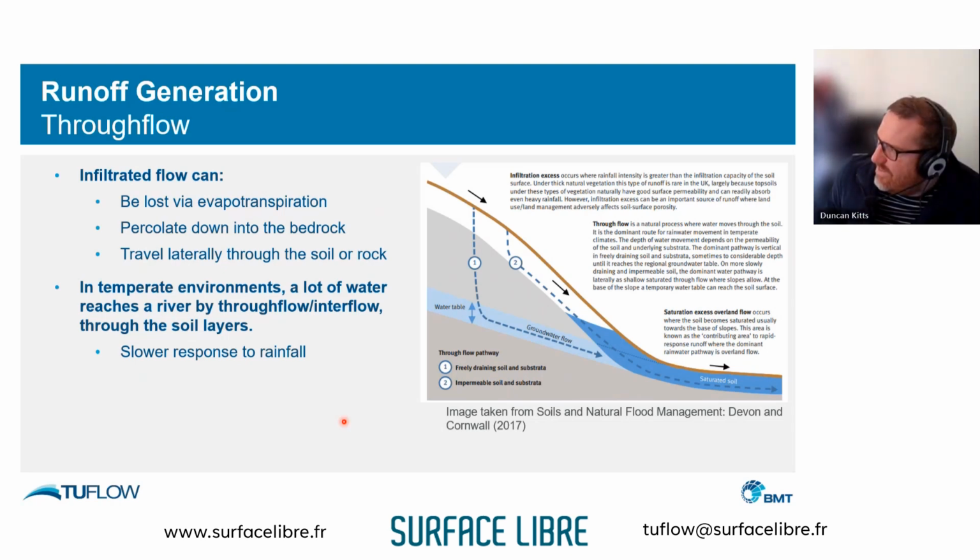I think I will add on this subject. Always do some sensitivity test on the values, just to check that the model is reacting as we expect. Sometimes we can have some strange results, and not only with TUFLOW, but with all these kinds of models with direct rainfall.